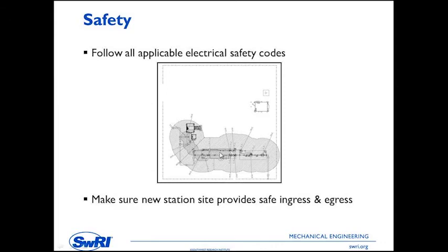Typically, when we talk about headers, we're going to try to limit the velocity in that header to something like 30 feet per second or less.